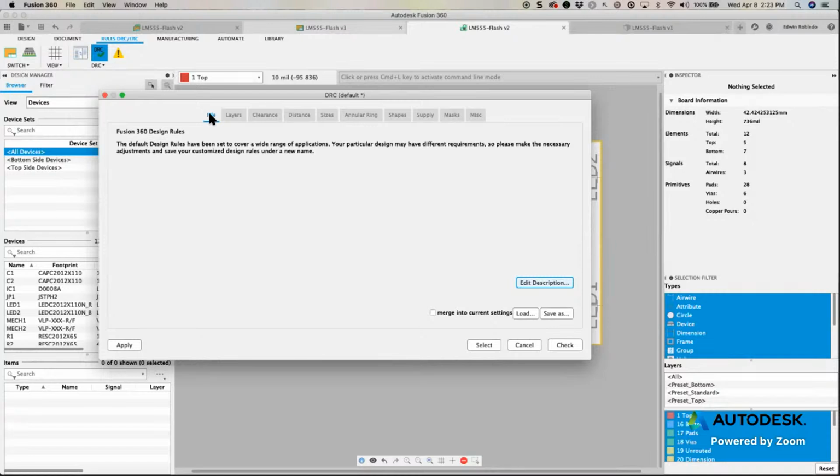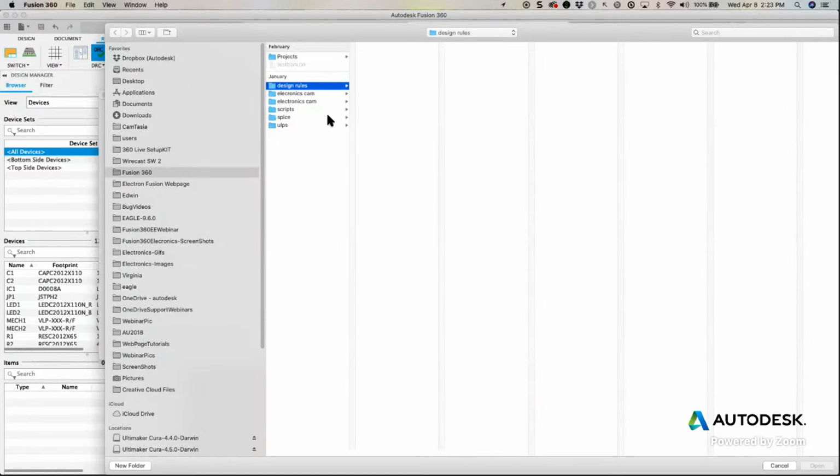So you could visit the manufacturer's website, a board house, OSH Park, Royal Circuits, Screaming Circuits, whoever you're going to be using, and it's quite possible they're going to be identifying their DRC file under Eagle. The Eagle DRC files are compatible with Fusion 360, just to let you know. The extension of that file is going to be DRU. Once you download that DRU file, you're going to click here where it says load, and find that DRU file that you've downloaded.